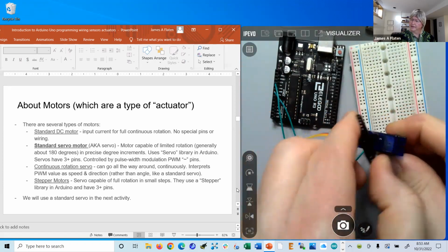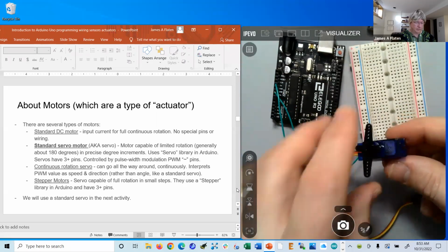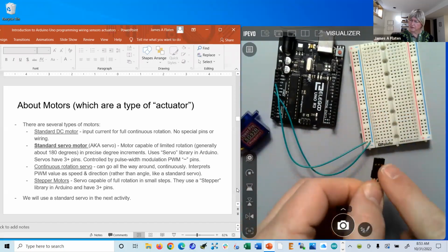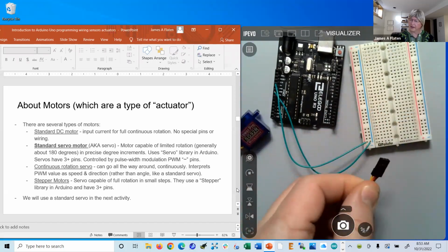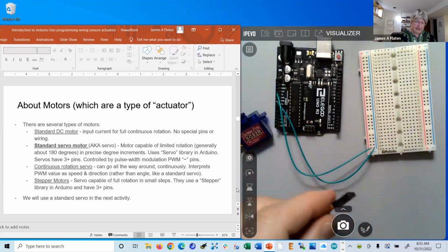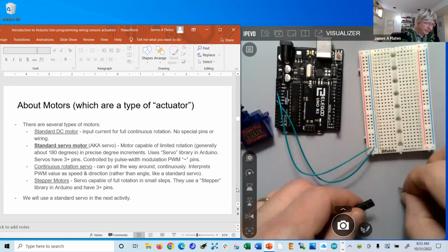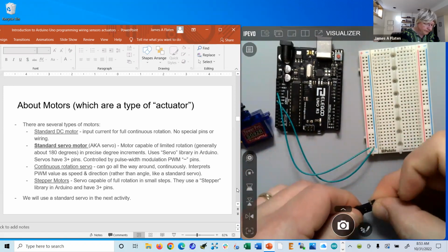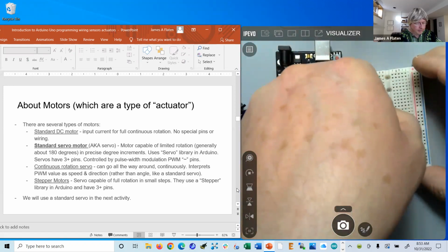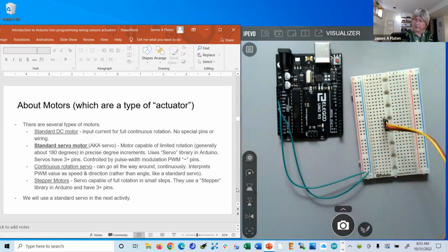Okay. So this particular activity is use the microcontroller to make the servo rotate. That's fine. And so to do that, I need to plug the servo into the breadboard. And right now, this is called a female header, and this is essentially all female. So I need to add a male to male adapter. So if I plug that in here, and then I plug this in here, now I will be basically ready to start wiring the servo.